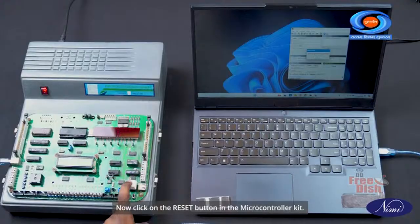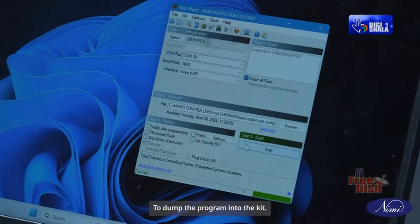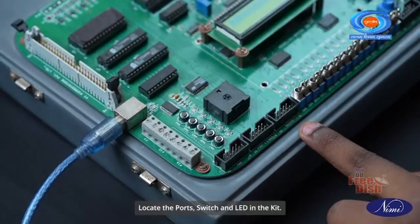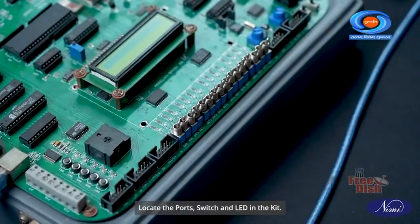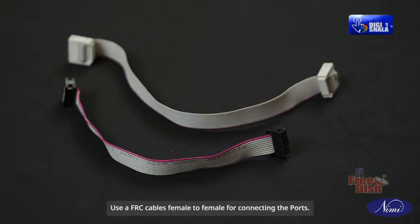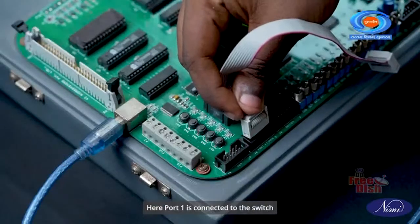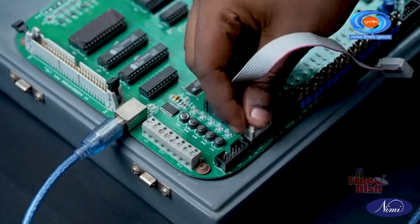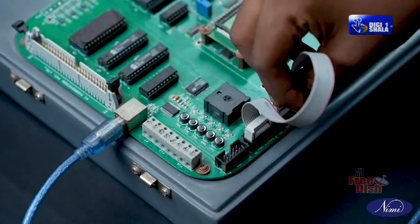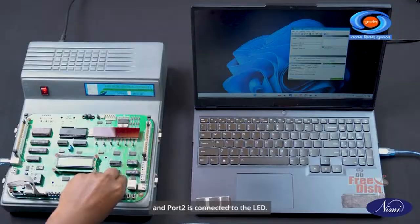Now click on the Reset button in the microcontroller kit to dump the program into the kit. Connect the ports according to the program. Locate the ports, switch and LED in the kit. Use FRC cables, female to female, for connecting the ports. Here, port 1 is connected to the switch and port 2 is connected to the LED.